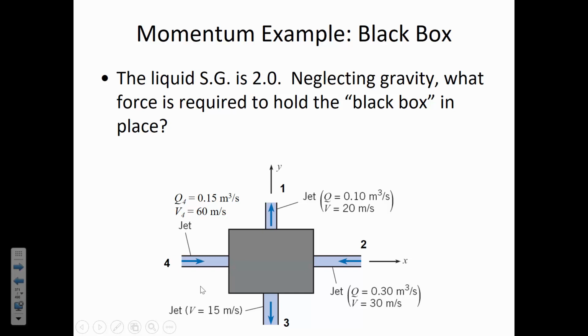So what you'll need to do is use the continuity equation to tell you what's the flow rate at 3. And since we don't have any information given in the problem statement or in the drawing about accumulation inside of the control volume, in other words, in the absence of any kind of flywheel being specified or a tank where flow is being stored, you can assume that the flow in and the flow out are equal. And so that'll be the continuity relationship you use to solve for Q3.